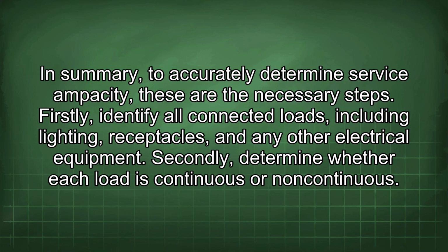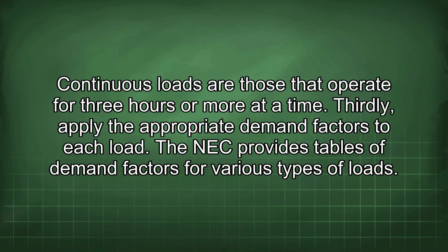Firstly, identify all connected loads, including lighting, receptacles, and any other electrical equipment. Secondly, determine whether each load is continuous or non-continuous. Continuous loads are those that operate for 3 hours or more at a time. Thirdly, apply the appropriate demand factors to each load.